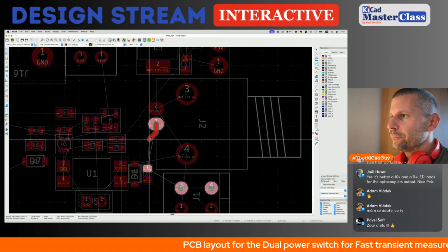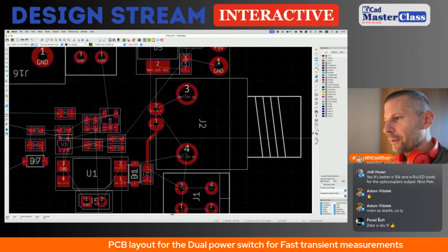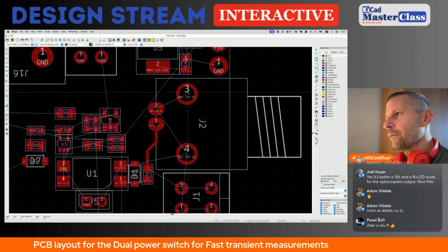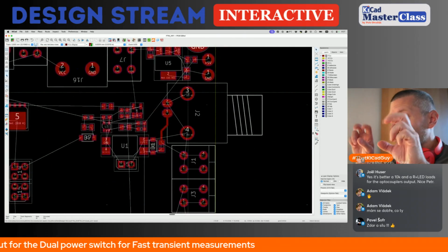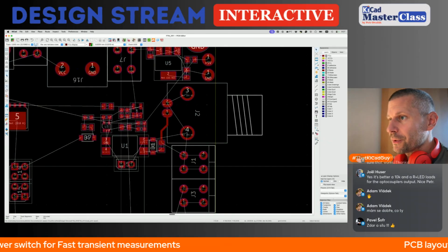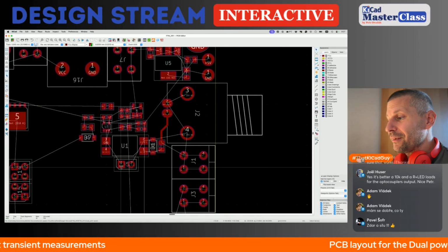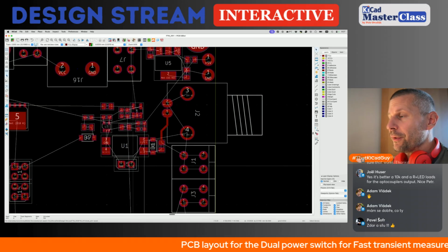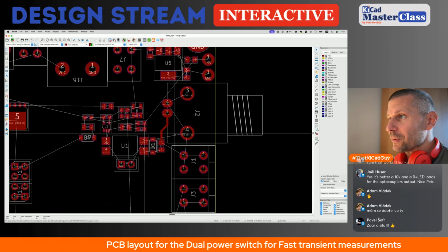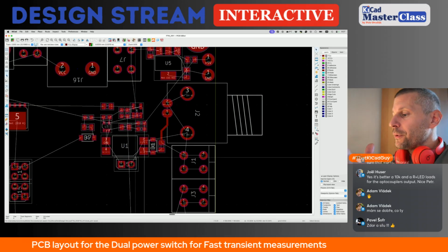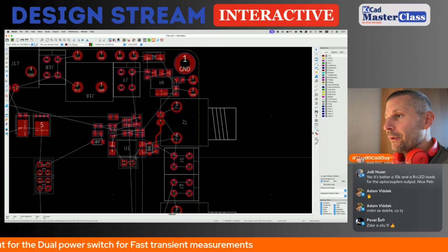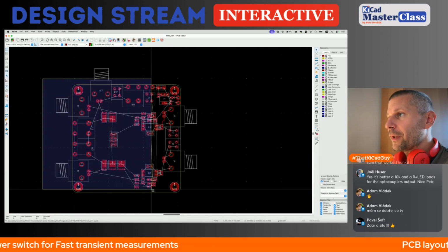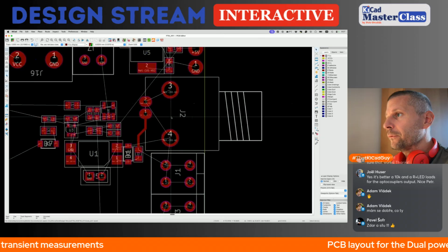Yes, that is connected to the ground in the quotes, because the true ground connection is done by placing a jumper here. Otherwise, it will be isolated from the instrument ground on the rest of the PCB. Okay.